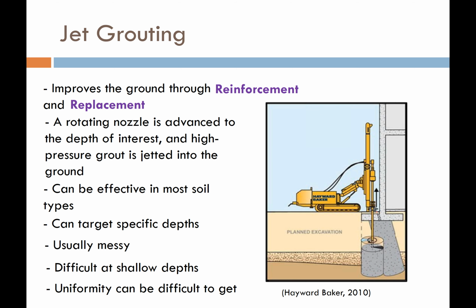It's a similar device, but our nozzle, instead of just being a straw that puts out gloopy balls of grout, has a spray nozzle on the end of it, and it sprays under very high pressure. It's going to spray grout into the ground, spinning around and spraying this jetted grout into the ground and producing these soilcrete columns as the nozzle moves up and down into the soil.